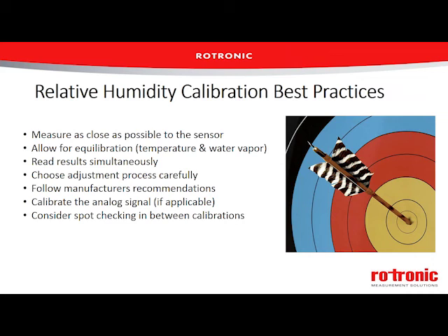Some of the best practices, and probably the most important one, is to properly allow everything to come to equilibrium. And I'm not just talking about water vapor or water content here. Temperature is a key parameter for any relative humidity calibration. Going back to Dalton's law and the definition of relative humidity, where we've got the amount of water in the air or the space above or open gaseous space